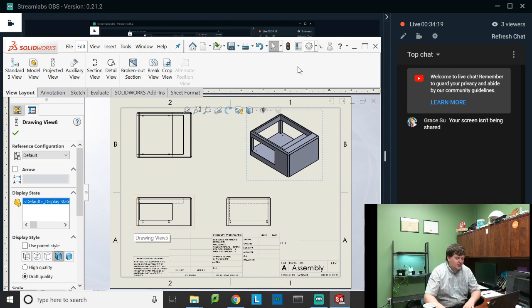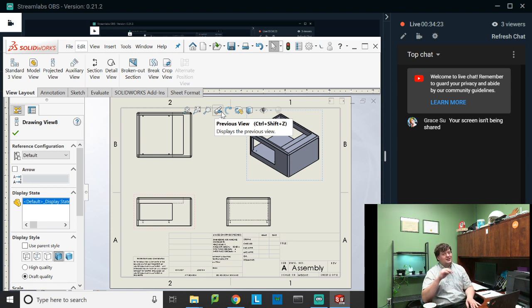It doesn't hurt any. Now this is actually opening up the actual part. When I opened this part, I did not specify that part to be red. I only did that in the assembly. So here, this part has no idea that it's listed as red elsewhere. That was not information that was stored in this part. It was only stored in the assembly file.